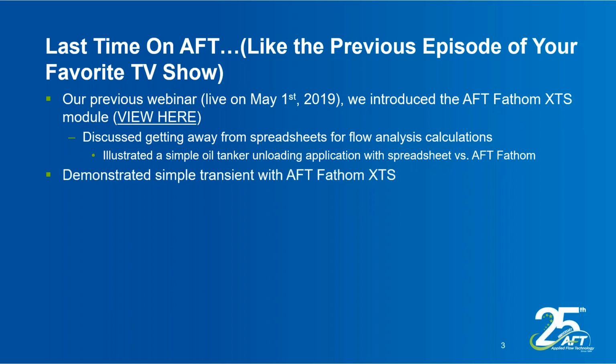What I then did was, for the oil tanker example that I initially demonstrated with a spreadsheet and AFT Fathom, I did a quick transient analysis of that system using the AFT Fathom XTS module. All it was to calculate how long it took for the oil tanker to unload all of the oil into the storage tank. That was a very simple question to answer with the XTS module.